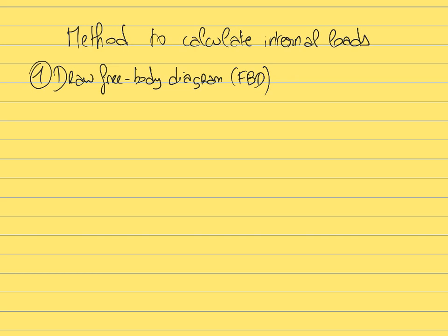When I say what you are isolating, I mean that you need to define the system that you are considering, and everything inside the system will be considered as internal. For example, the internal forces will be the forces that are inside the system, and everything that is outside the system will be the exterior, and so they will be contributing external forces. So you need to draw the free body diagram.